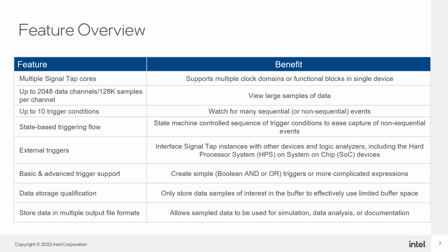Finally, the data captured by the logic analyzer can be stored in many formats and exported for use in other applications, such as simulation, power analysis, or design documentation. We'll discuss most of these features in this training, but check the Intel Quartus Prime Debug Tools user guide and the Intel FPGA website for more details about these and other features of the tool. Links to these resources will be provided later.